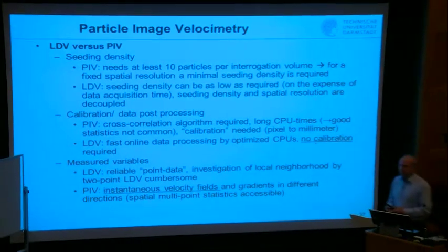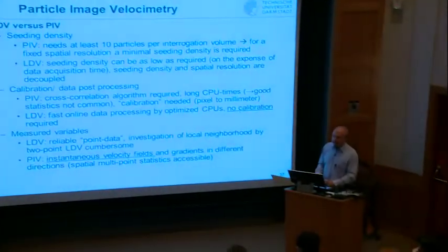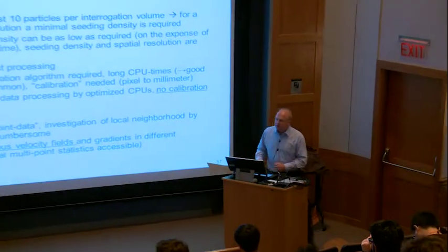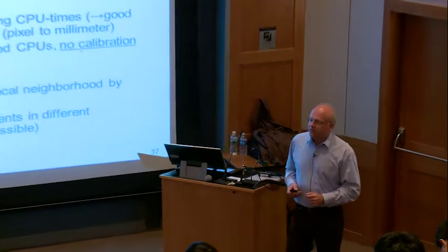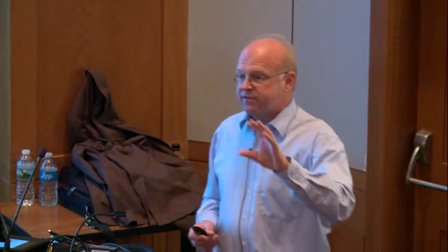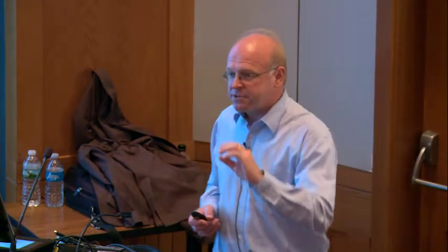Yes? I think on slide 33 you mentioned that one of the stages of post-processing is Gaussian smoothing. If you use Gaussian smoothing, the fluctuations should flatten out, and if we are, for instance, interested in Reynolds shear stress, it should underestimate. Is there any better way to do post-processing to get rid of that noise without underestimating? So the question is, if you use any kind of filtering in the post-processing, of course that harms the fluctuation level, which is reduced as well.